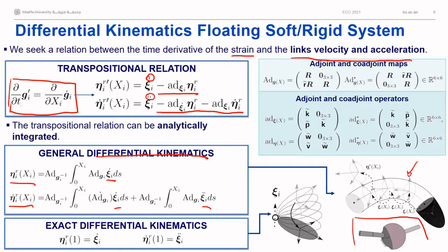Now, let's recover the classical one-dimensional case. So for a one-dimensional joint, it ends up that those relations are flat. So all of this part disappears. And then we recover the standard relation between the joint twist and the relative velocity between two bodies, and similarly for the acceleration, the one that we usually use in rigid robotics. I think this is a nice picture that connects together some of the ideas here.